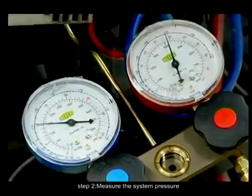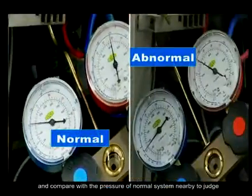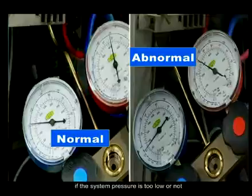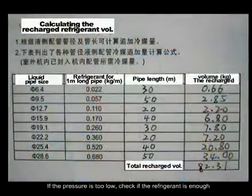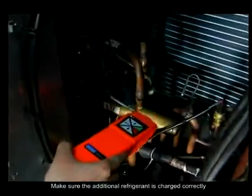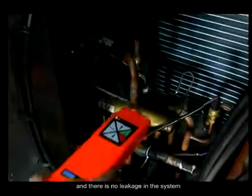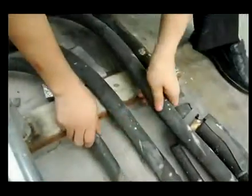Step 2. Measure the system pressure and compare it with the pressure of a normal system nearby to judge if the system pressure is too low or not. If the pressure is too low, check if the refrigerant is enough. Make sure the additional refrigerant is charged correctly and there is no leakage in the system. If it is normal, please go to the next step.